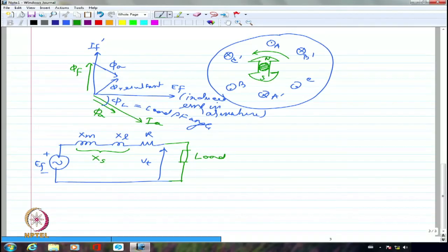In the case of a synchronous machine, because your synchronous reactance is the magnetizing reactance plus the leakage together, I am going to have a very large value. It can be greater than 100% sometimes. So you are going to have a very large synchronous reactance, which tells me that when I calculate regulation, eventually the drop could be pretty large.